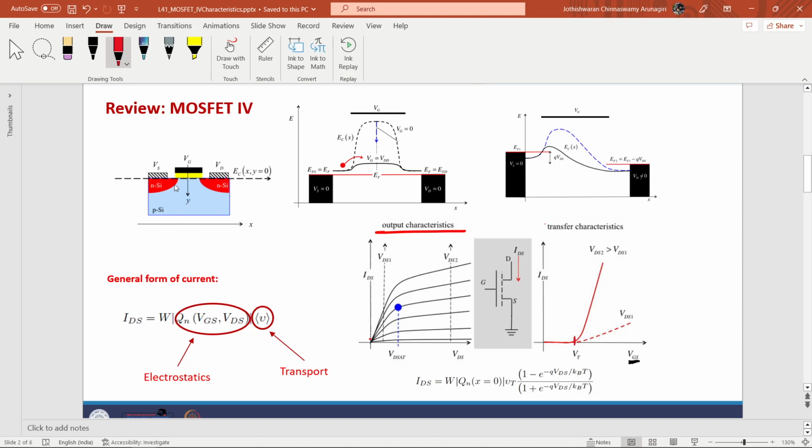The gate voltage will decide how many carriers are present between my source and drain, so that a voltage applied here can be conveyed via a current from the drain to the source or vice versa. So this threshold voltage is the point at which that phenomenon starts.